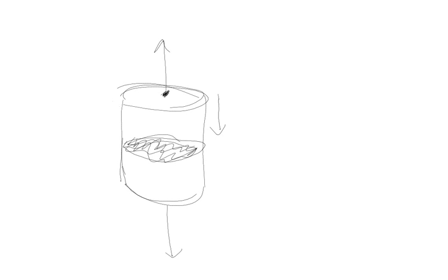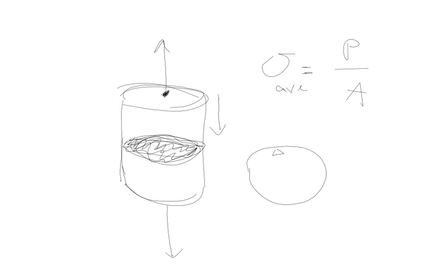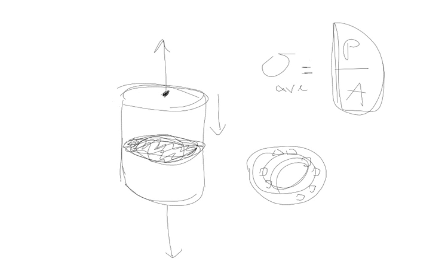And that means by the time you get a certain distance away, that force is evenly distributed over the cross-section. So even though when you do sigma is P over A, that's also an average. It's averaged over the whole cross-section, meaning you take this cross-section, break it up into a bunch of little pieces, take a look at the force on each of those little pieces, and then average it all up together, that's the value you get. Because that force is evenly distributed, the average is actually the same as the value anywhere on this surface. So using an average doesn't really mean anything. It's an exact value.